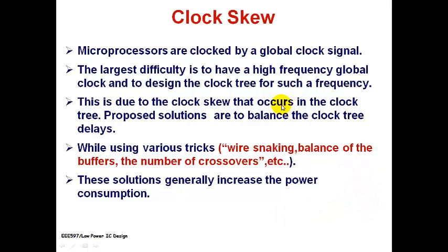And this high frequency signal, when it goes through different paths and different lengths of wires and different types of loads at its ends, would now be acting very, very differently. So my main concern would be to let all the clock signals reach all the timing elements like flip-flops and latches at the same time.